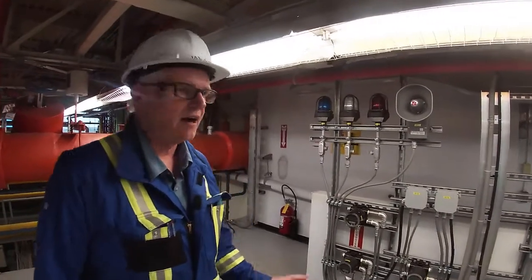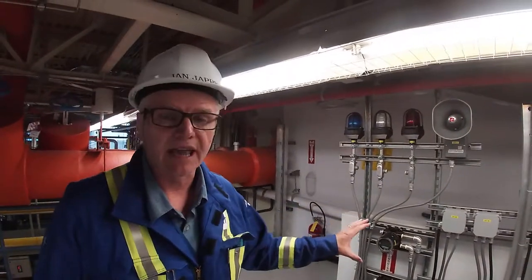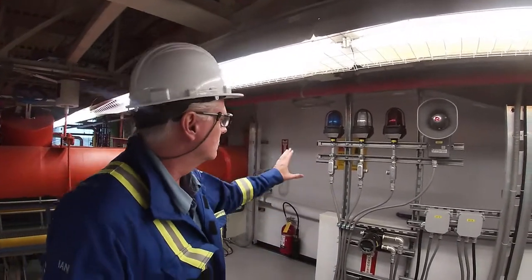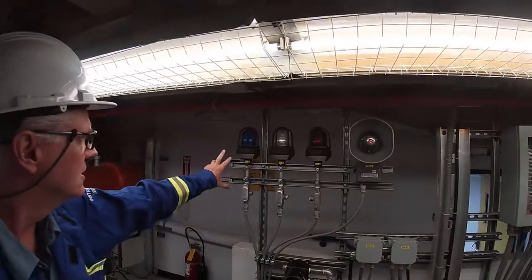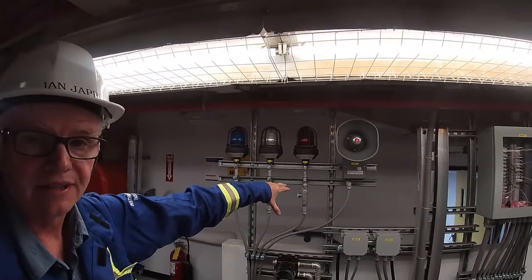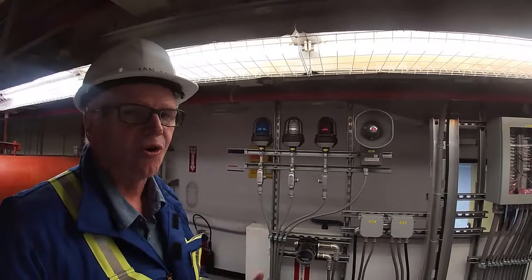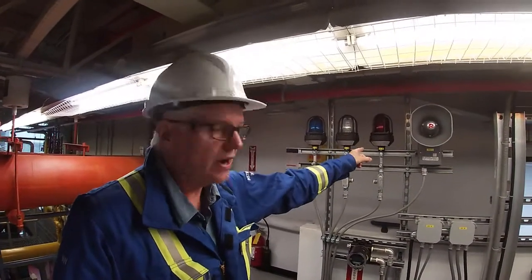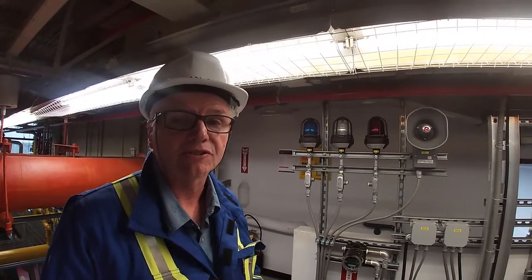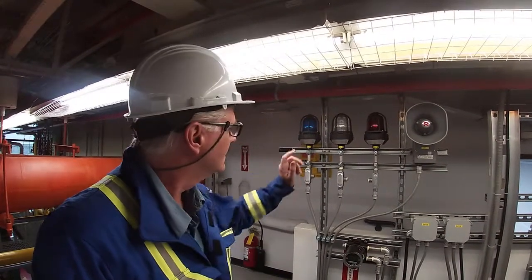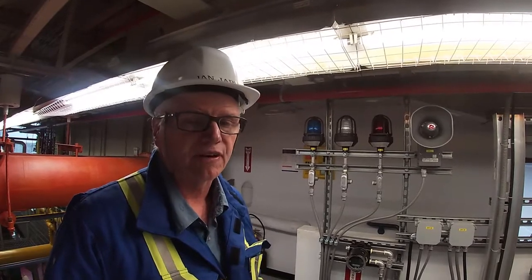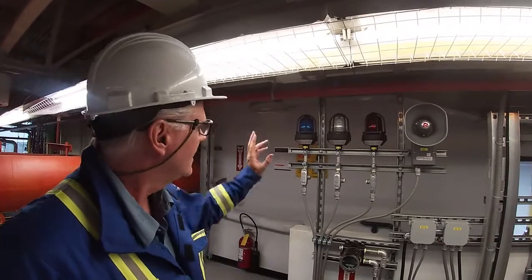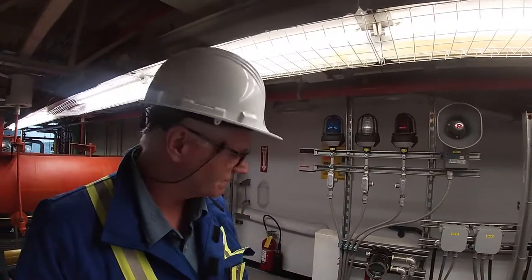Okay, so now we're looking at our fire and gas detection system that ties into the Delta V SIS. We have 3 strobes: blue, white, and red. The colors kind of don't match, but I'll run through them with you. Red is for LELs or combustibles. The white strobe is for fire detection. You would think it would be red, but it isn't, it's white. And blue is for toxic gas.